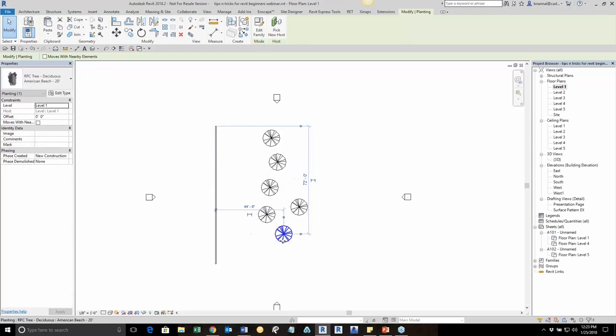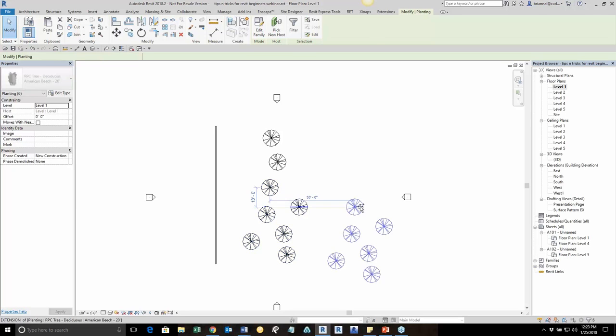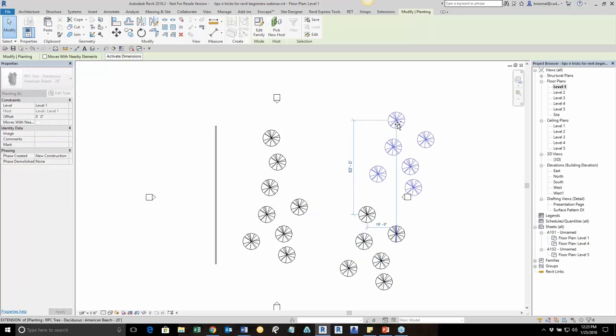So a little bit faster than just right-clicking copy or going up here to the copy function or keyboard shortcut of Ctrl+C. If I add additional items to my selection by holding the Control, I notice the plus sign on my mouse there. I'm adding multiple items to my selection and holding the Control and dragging, and I can make multiple more copies that way.